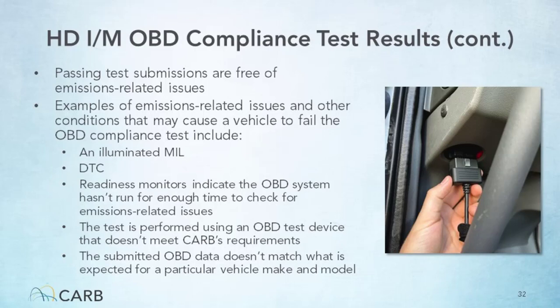These checks are self-performed by the OBD system, and the criteria for completing and validating certain readiness monitors varies. As a general rule, clearing DTCs with a diagnostic scan tool or by disconnecting the vehicle's batteries shortly before performing an emissions test can result in a rejected test and delays in obtaining emissions compliance. If a rejected test is a result of recently cleared DTCs, an additional test will need to be performed after the readiness monitor tests have completed. In conclusion, testers should not clear diagnostic trouble codes and should be aware that performing the Clean Truck Check emissions test shortly after DTCs have been cleared is not advised.